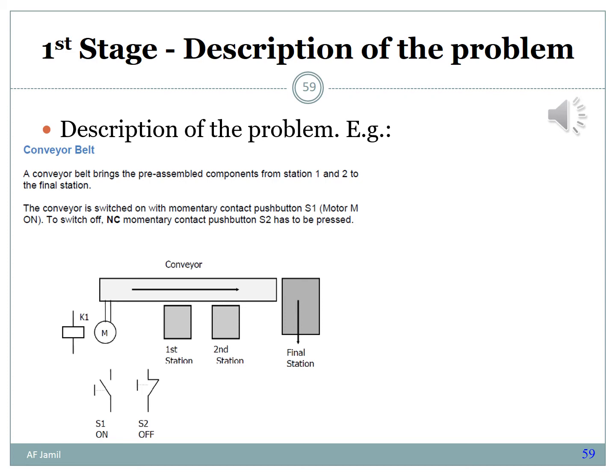From the description, the condition stated that if the momentary contact push button S1 is pressed, then K1 must be energized. Another condition in the same description stated that if the normally closed momentary contact push button S2 is pressed, then K1 must be de-energized.